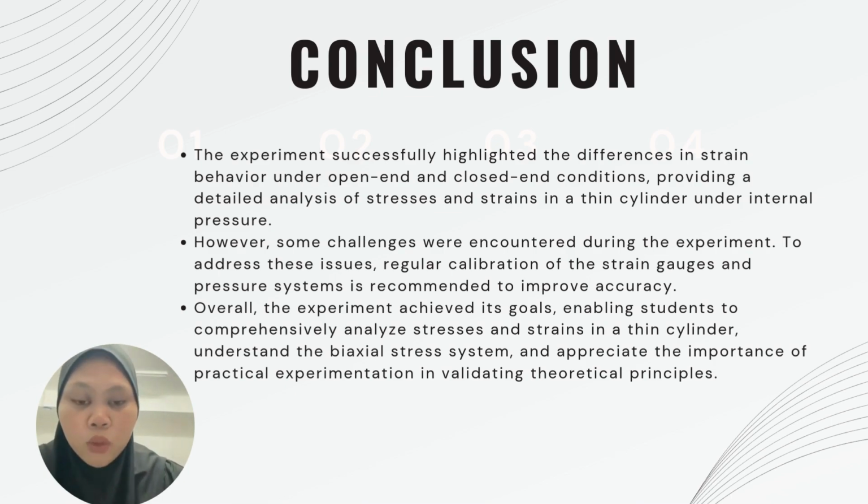We were able to compare theoretical and experimental strain values for both conditions, gaining practical insight into stress-strain relationships, biaxial stress systems, and the mechanical properties of materials such as Young's modulus and Poisson's ratio. However, some challenges were encountered during the experiment, and ensuring uniform pressure distribution and accurate alignment of the strain gauge was challenging.